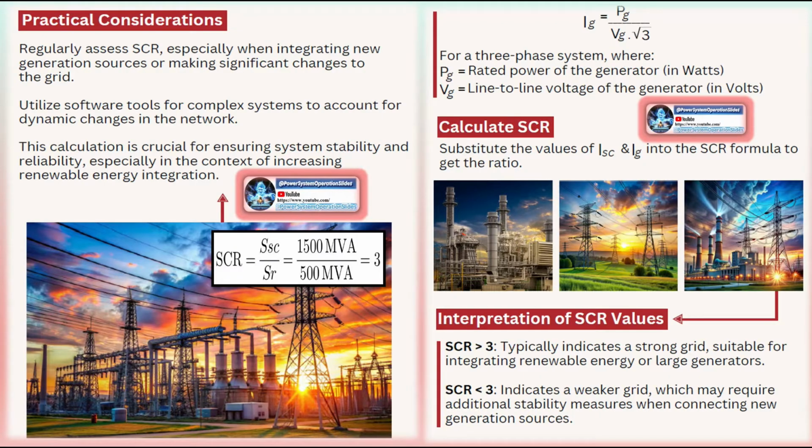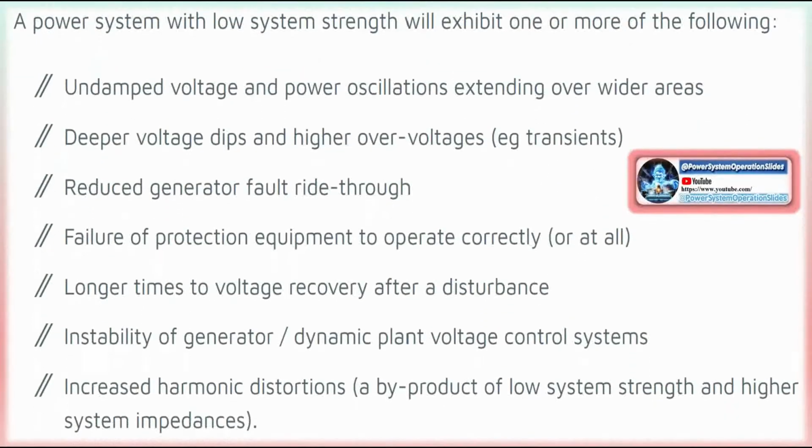Large coal and gas generation create 5 times more fault current compared to wind and solar. A 100 megawatts generation would provide in the region of 500 to 700 MVA of short circuit level. Wind farms are limited by the rating of their electronic components, so the same level of generation may provide only around 100 MVA of SCL.